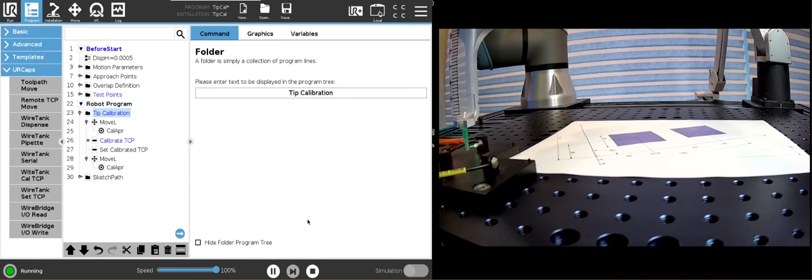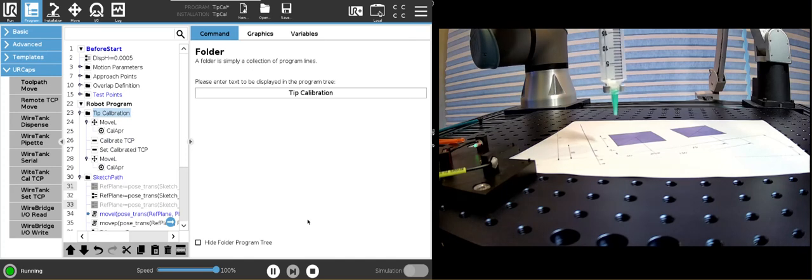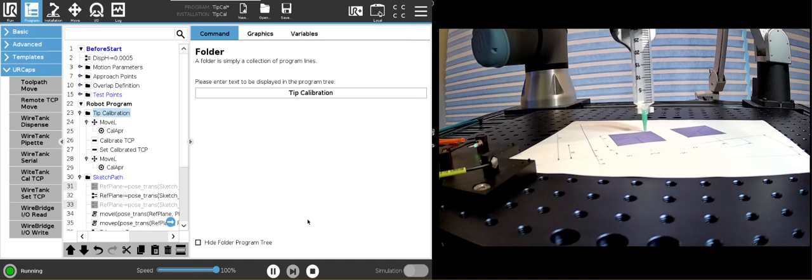So now we will measure our offset here, we will measure our offset on the other edge, and now we will go and we will very accurately again dispense following the path of the blue square so that it matches perfectly the height. And that is essentially the whole role of the tip calibration.